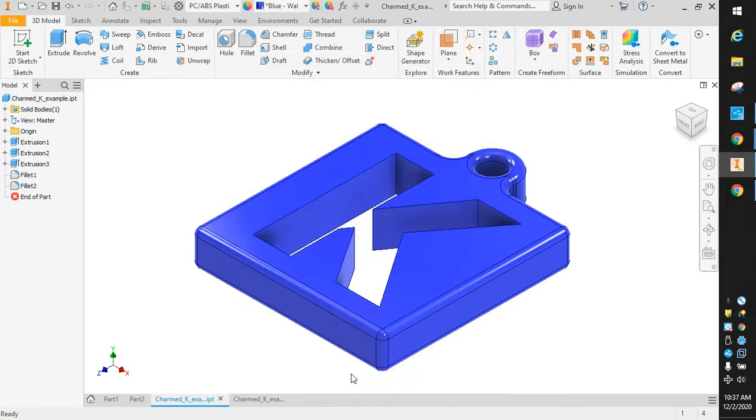And maybe I'll back up a step here. Set your material to ABS plastic. The density, the properties are very, very similar to PLA that we print within our 3D printer. Unfortunately, we don't have PLA as a material to choose from in Inventor currently. At a later date, we can create properties and create materials, but for what we're doing, this will be just fine. The properties, like I said, are very, very close.